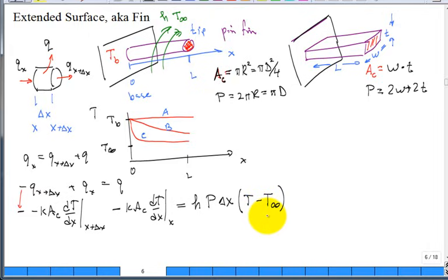Professor, I think the heat transfer is two-dimensional in this pin fin. I know it is, but we're neglecting the 2D heat transfer. We're approximating it as 1D. What's the temperature difference between the temperature at the center line of that fin anywhere along it and the outer radius, anywhere along it?